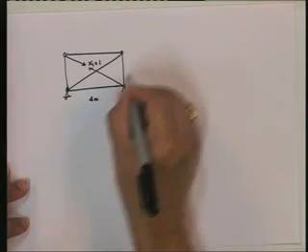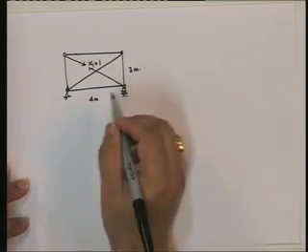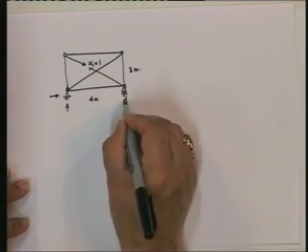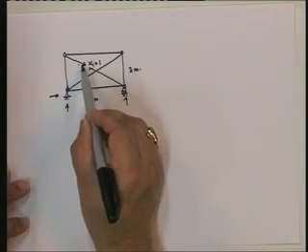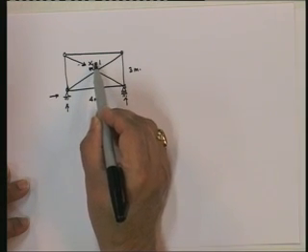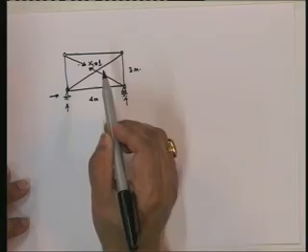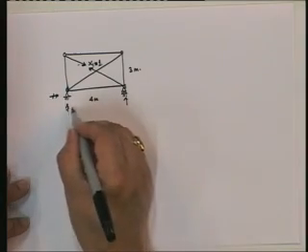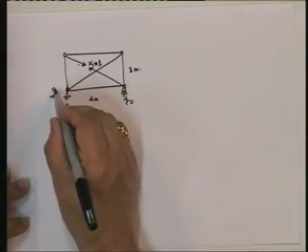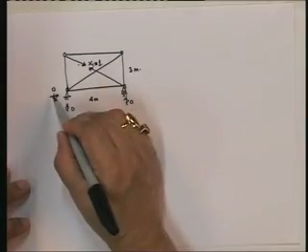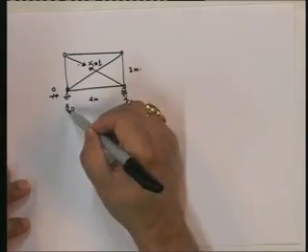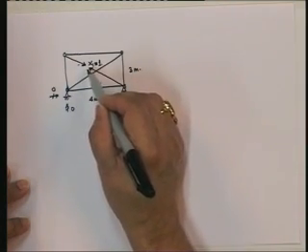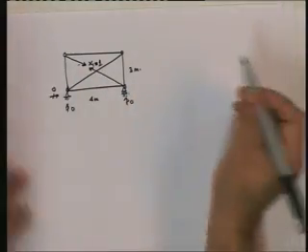Remember that this is still 4 meters, it's still the original structure. Okay, so this is 4 meters. What about the reactions? Look, this is a force that I am applying in a member. It's an internal force. So it's equal and opposite. So therefore, there is no net force acting on the structure, and therefore all the support reactions are actually 0. Because sigma fx gives me this equal to 0, sigma fy gives me this plus this equal to 0. Then I take moments about this point. Since these two are acting equal and opposite at the same point, this is going to be 0, this is going to be 0. That's not an issue.